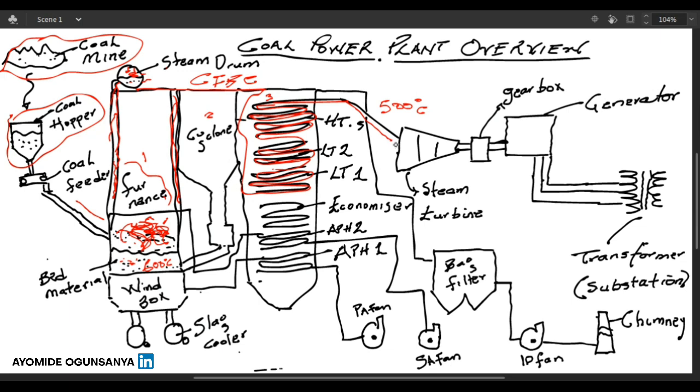Alright, so steam is then sent into what? That dry saturated, superheated, dry superheated steam is sent into your turbine. And when it's sent into your turbine, it creates what? Mechanical motion inside your turbine at extreme speeds, ranging even up to 7,700 RPM. Alright, and this is then what? This mechanical rotational output is then transferred, so we can have a gearbox which then reduces the speed to the designed speed of your generator.